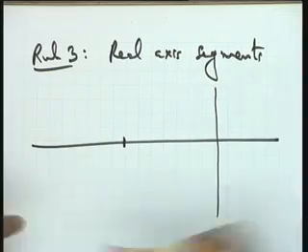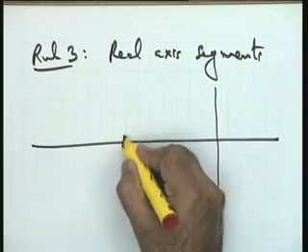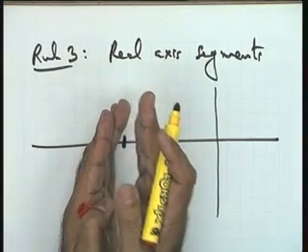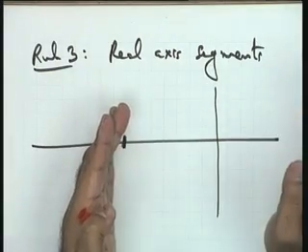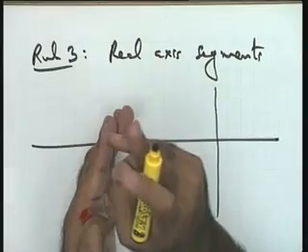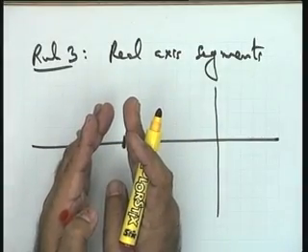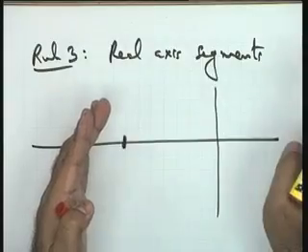See my rule number 3 please. I make a statement: if the number of real axis open loop poles and zeros to the right of this point is odd, in that particular case this point lies on the root locus.